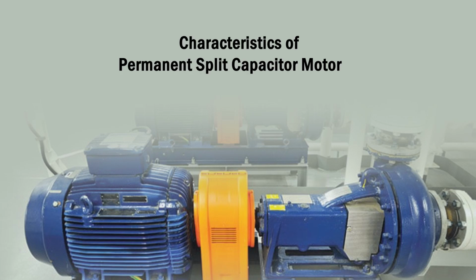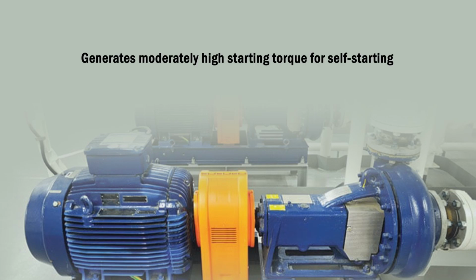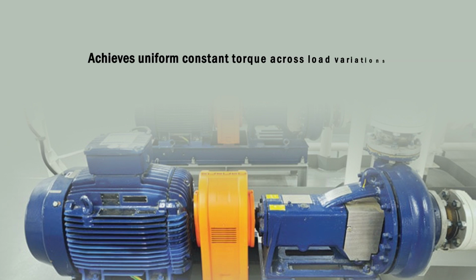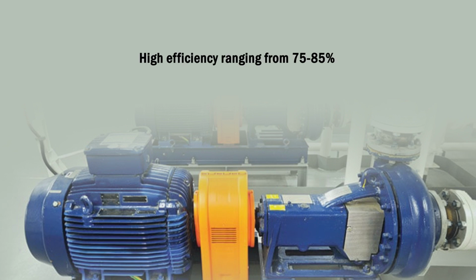So the characteristics of this motor are: it generates moderately high starting torque for self-starting. It achieves uniform constant torque across load variations. It maintains consistent speed even under fluctuating loads. It gives high efficiency ranging from 75 to 85%. Its power factor is above 0.8 at full load. And it has the capability for medium inertia load applications.